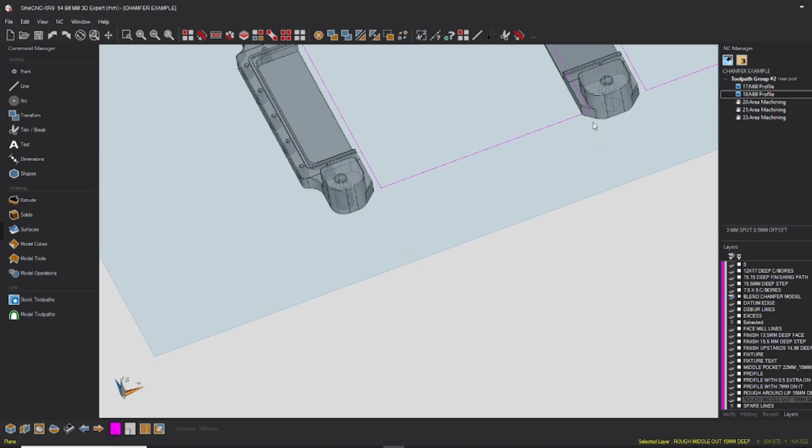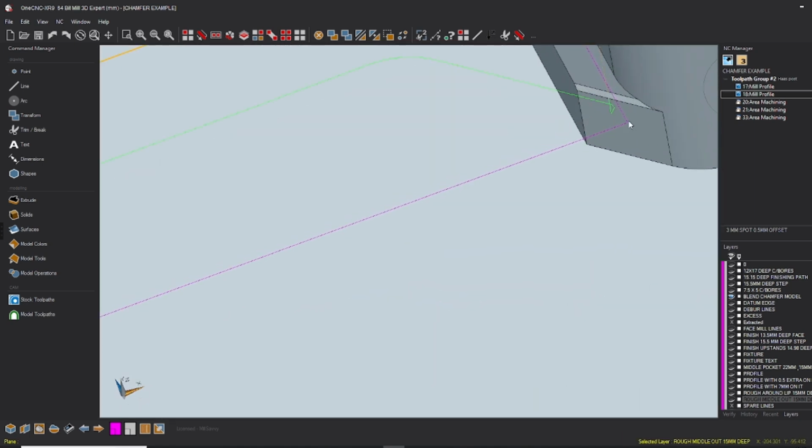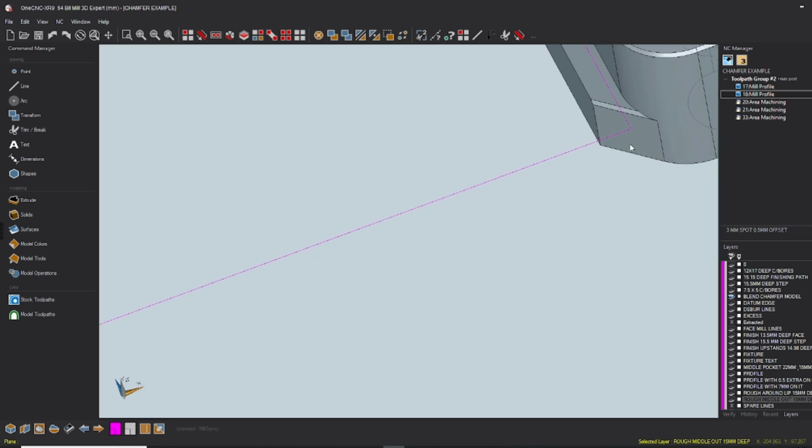Now this is where you have to be a little bit more careful with how you draw this tool path, and you can see I've done the 90-degree approach so I can control, and I've laid off this wall by a known amount. And then what I do is I come in with the area machining and I blend this in. I blend my chamfer in. I can touch here, can't I? Go along this line and then come round this and chamfer all this. I know I can do that, but I can't get the tool right up against this edge.